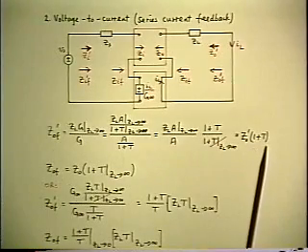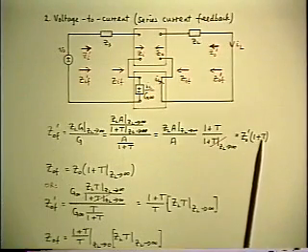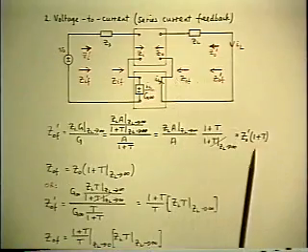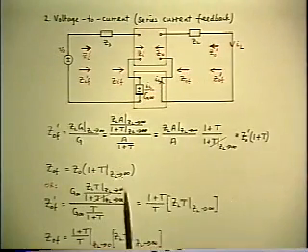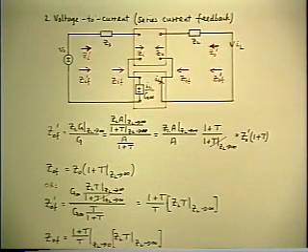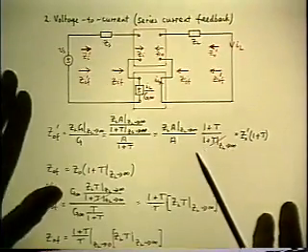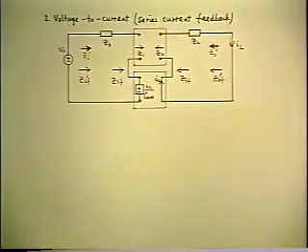The net result is the output impedance with feedback is bigger than the output impedance without feedback. And you get the same four results, and the same interpretation, of course, that goes with all of them. Okay? The input impedance formulas, of course, are identical to the ones that we've done already.